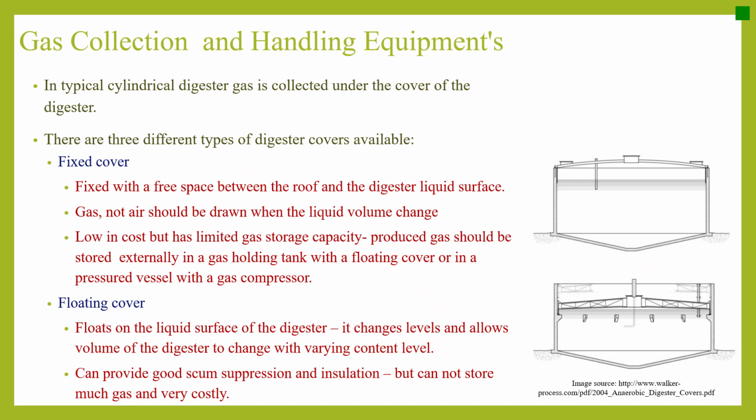And then comes the floating cover. It floats on the liquid surface of the digester. It changes levels and allows the volume of the digester to change with varying content level. It can provide good scum suppression and insulation, but cannot store much gas and is very costly.